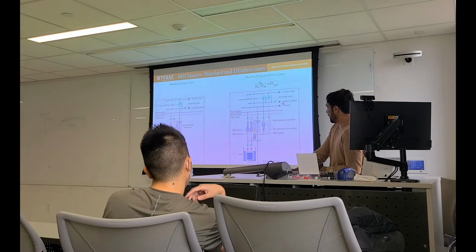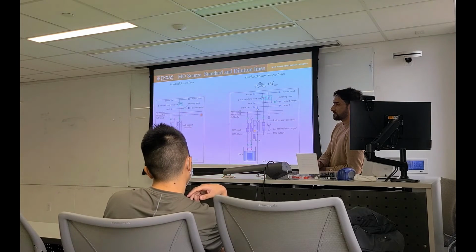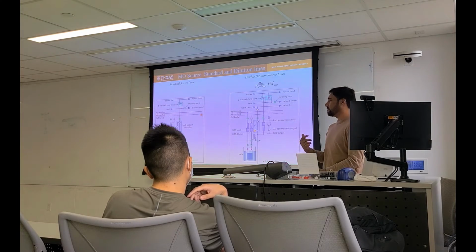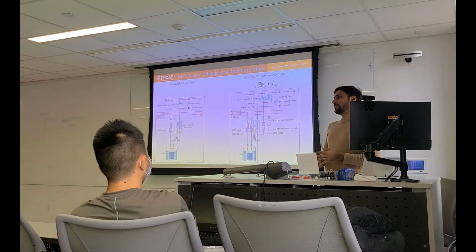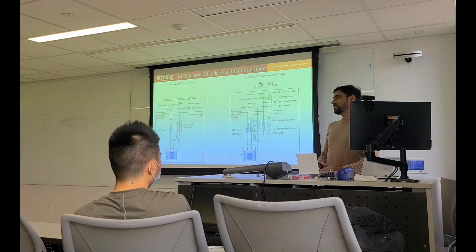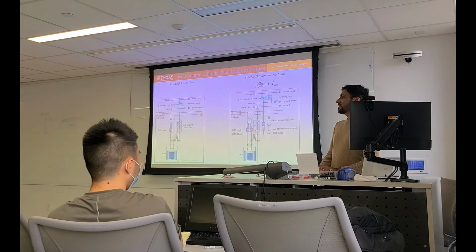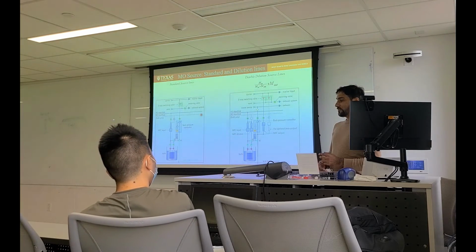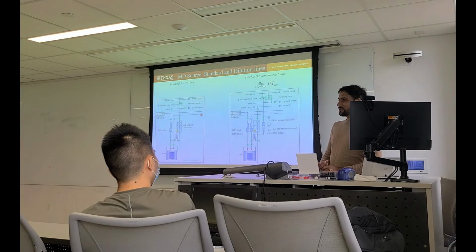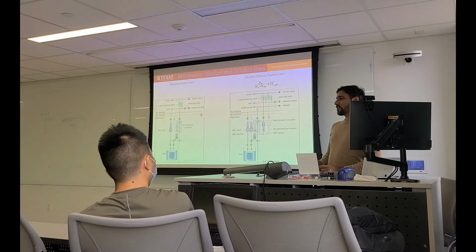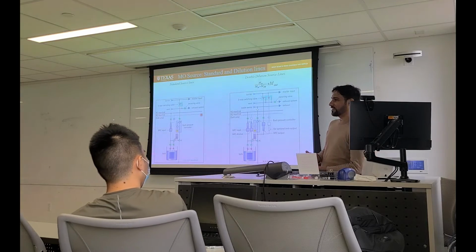There is another metering well. You can see in any line before the exhaust. And the role of metering well is that sometimes because of the makeup lines you are flowing your carrier gas. The company who gives you a MOCVD, they will always ask you to flow the higher carrier gas. Okay? But we can figure out a way to consume very low amount of carrier gas.